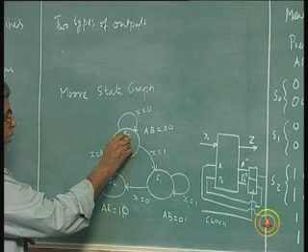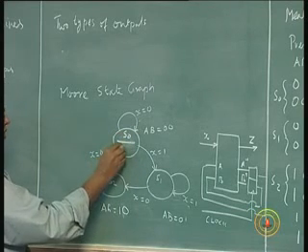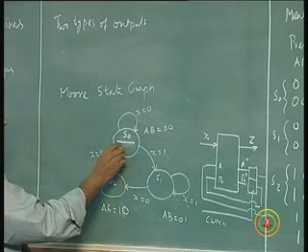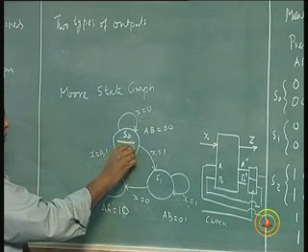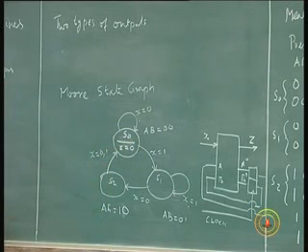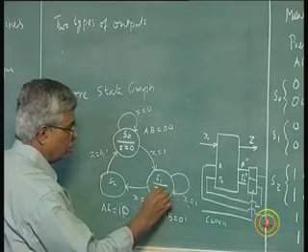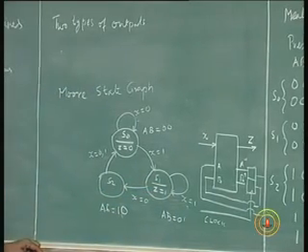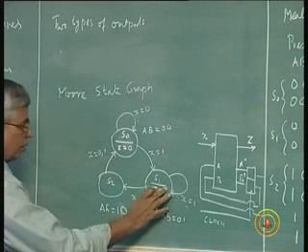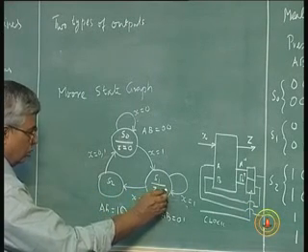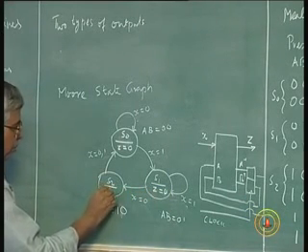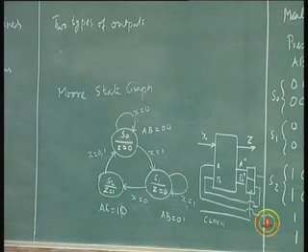So now this is how you will find a Moore graph with Z equal to 0. In the S0 state the output is 0. In the S1 state also the output is 0. In the S2 state maybe the output is 1. Just arbitrary again. I'm having an output called Z, which is 0 here, 0 here, 1 here.